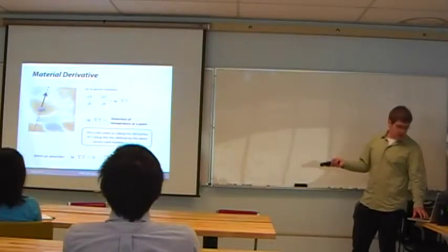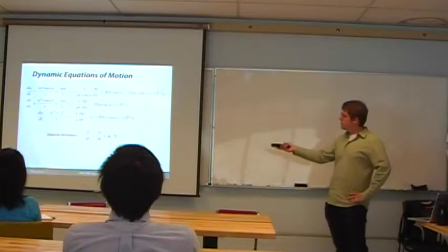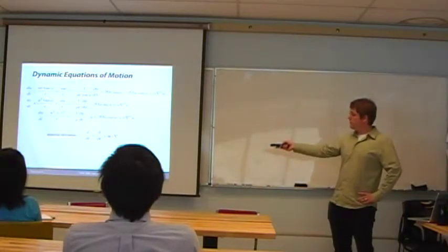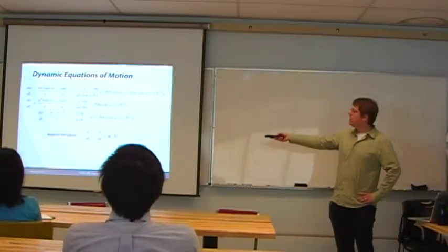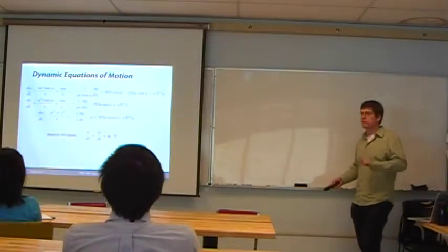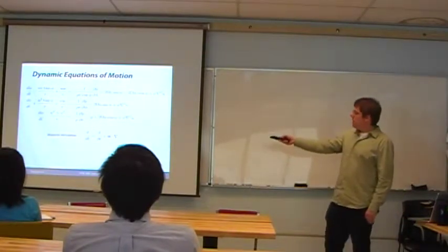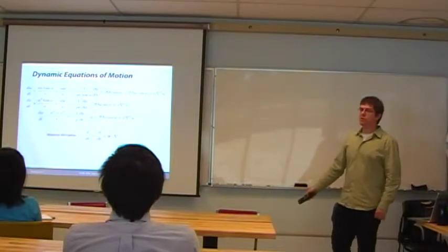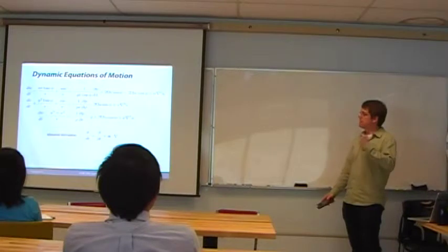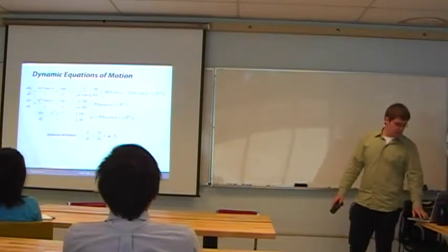So if we then turn our attention to the dynamic equations of motion that we derived previously, and insert the material derivative, we're going to obtain an expression for the pointwise change, the Eulerian change, which is represented here by the partial derivative with respect to time, for each of the u, v, and w components at a certain fixed location in space. So then, with these four equations of motion, we can obtain the Eulerian update of the velocity field at each point in space.